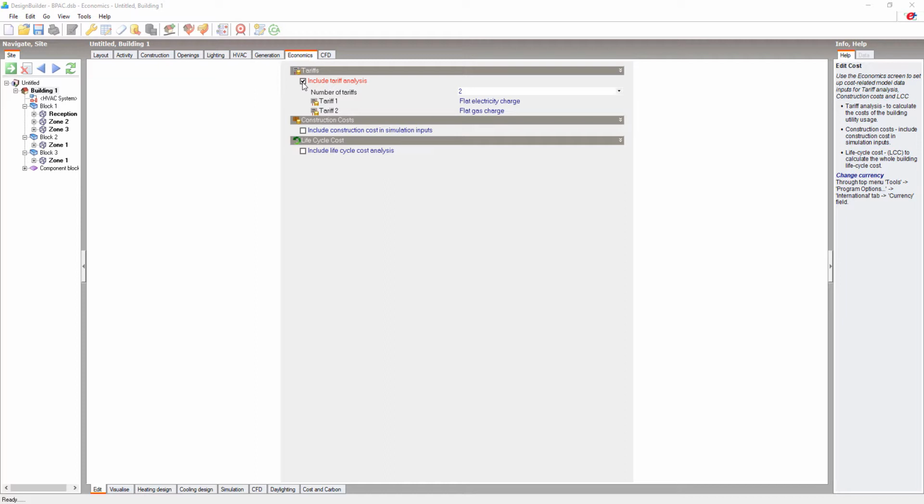So you've now seen me set up this model and make changes as I've gone along. What I've covered could easily represent an early stage building. So we could start to run calculations at this stage to check energy and comfort performance to help inform the design. To reinforce that, I'll run heating and cooling load calculations now before I set up a more detailed HVAC system. Starting with heating design, this is a steady state calculation for determining heating plant loads using winter design data.